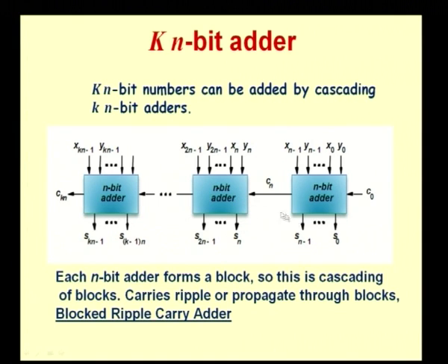Okay. You can look at this as first digit, second digit, third digit, and so on. If one digit requires n bits to be represented, I am talking about k such digits being represented. Each digit is handled by means of an n-bit adder that we have here. You can see what we are able to achieve by cascading these adders: you can now construct larger and larger adders. That is the advantage we get with this kind of circuit design.